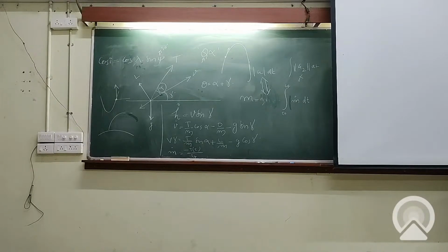So there is nothing you can save in terms of mass. Then when it comes to the second stage, even though it is a liquid stage, we have this flexibility of saving fuel. We usually go for fixed duration burns. We keep the additional fuel margin and go for fixed duration. The additional fuel is to cater for the dispersions during the flight. That is not part of the mission. It is just a reserve fuel.